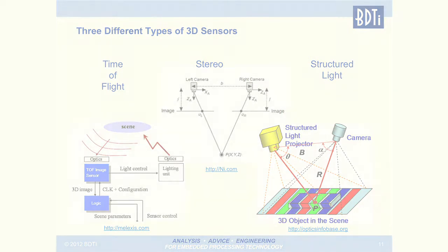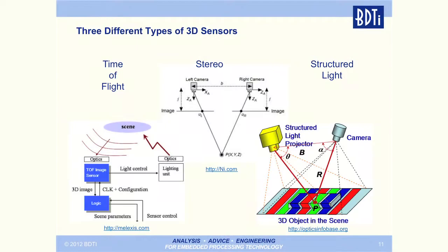Problems with stereo vision, as Gary said, as you get farther away, it's a logarithmic response. It's harder to detect depth. Other issues with stereo vision, again, that Gary mentioned, you have to correct for the lenses. It's really impossible to get the two cameras perfectly set up, so you have to correct for one of them, and that takes a lot of CPU cycles. And then again, you got structured light, which is what we're going to talk about next.